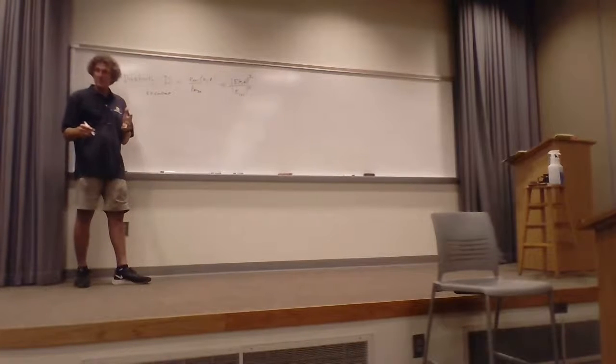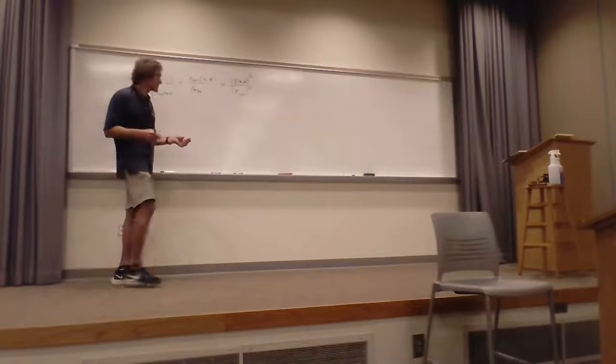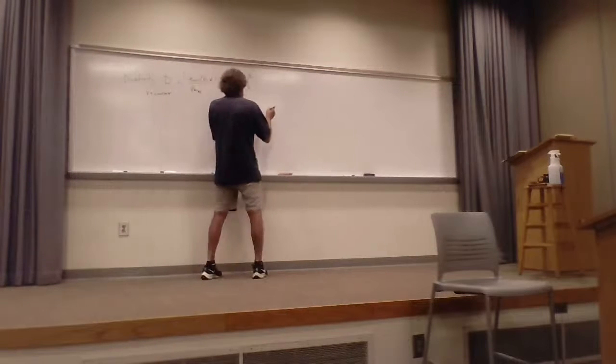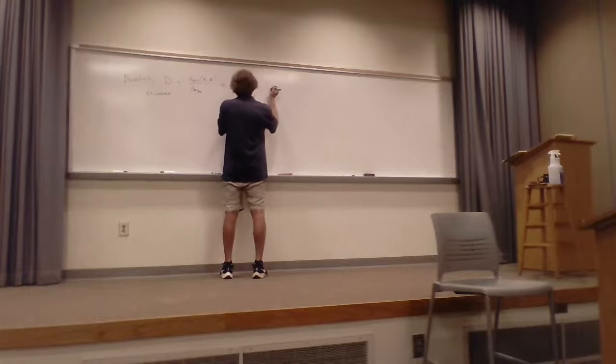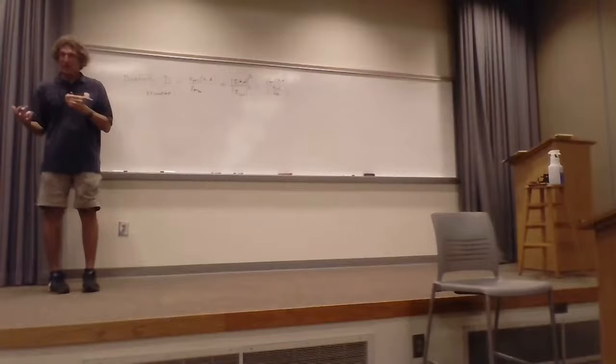One thing that's constant is the power. Y'all see this? If I put in the etas, they'll cancel, the 1/2s cancel. So I just put the E squared. And the thing I can do is say it's equal to P_AV right here of the antenna I'm using as a function of angle. Well, the isotropic power is really P_rad, the total radiated power over 4 pi. That would be the average power density for an isotropic radiator.